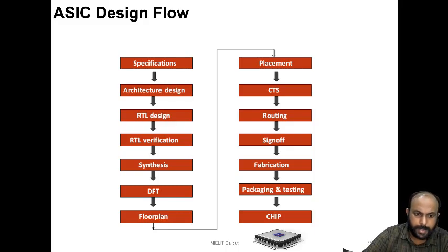Once RTL design is done, it is subjected to a variety of functional simulations, wherein the design engineer himself or herself looks for possible bugs or compilation errors, which are resolved at that stage. Once the design engineer is satisfied about the conformity of the design to the specification, he or she will push it to another team called RTL verification engineers.